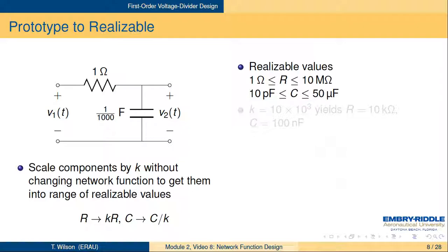And capacitors have similar distribution. They're sort of logarithmically scaled is what it actually is. So we like to get the resistors, and you don't really find resistors bigger than 10 megaohms, your sort of standard resistor size, and you don't find them smaller than 1 ohm. And there's reasons to go with bigger values, but you don't want to go too big because there's noise considerations that are beyond the purview of this class.